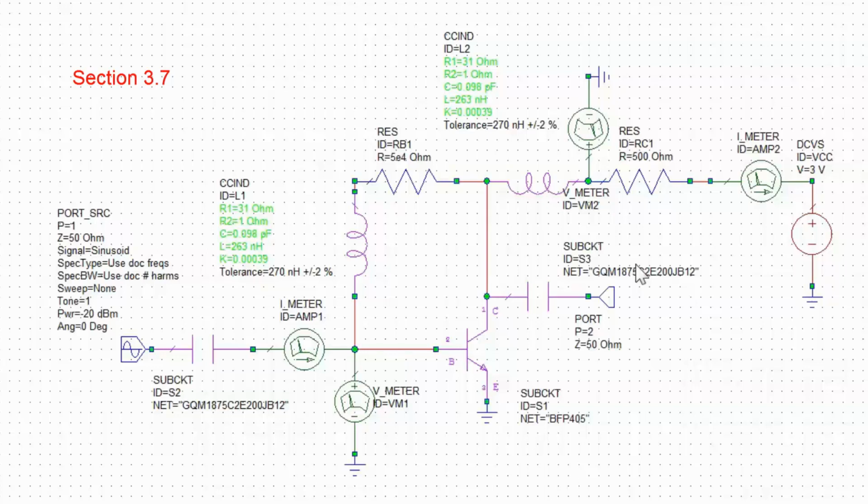And from the reflection coefficient you get the impedance seen at a particular port, but they can also measure the power transferred between one port and another. And this is another measurement that's obviously very interesting when you're designing amplifiers, because you want to see the power that you can transfer from one port to another.